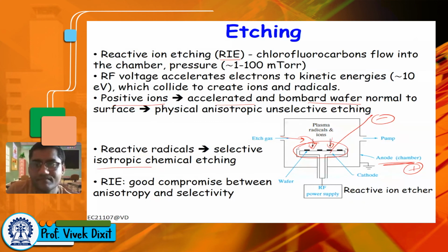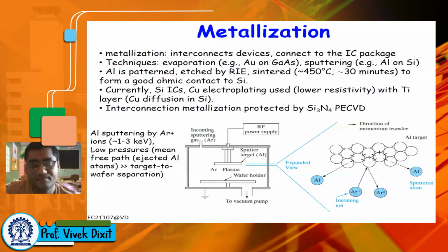So the last topic for the fabrication is metallization. So how is the metallization done? If you see here, this is your wafer, right? Then in this case also you use plasma only. So in plasma you have the sputtering gas, usually inert gases, argon, which are ionized by the plasma, and they will hit the surface, right? So this surface can be any metal, aluminum, copper, right?